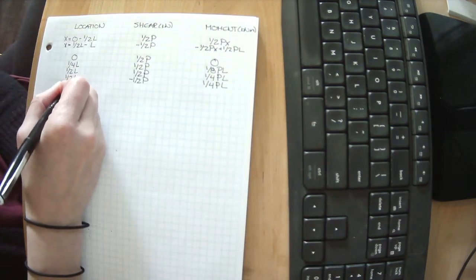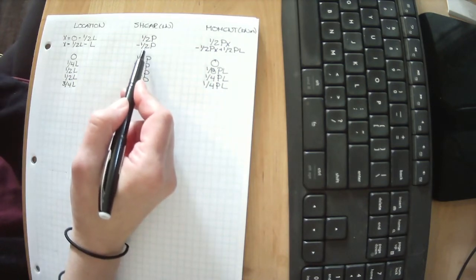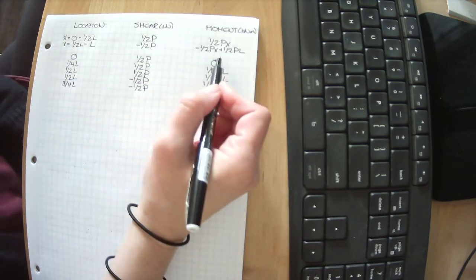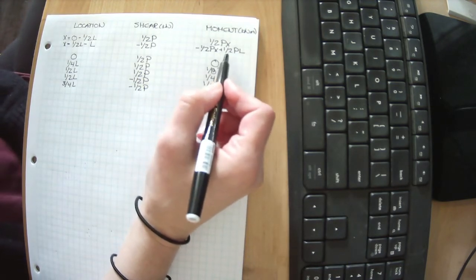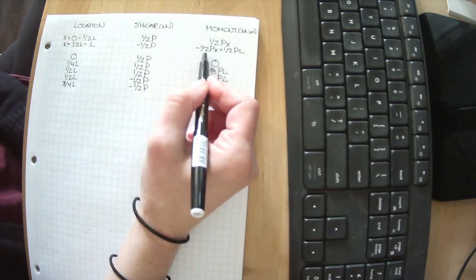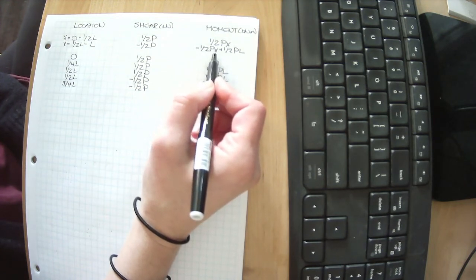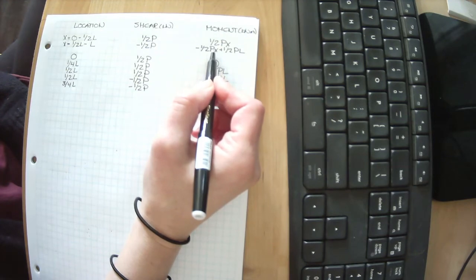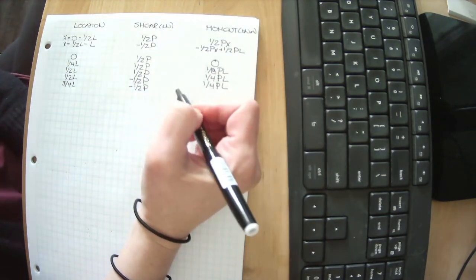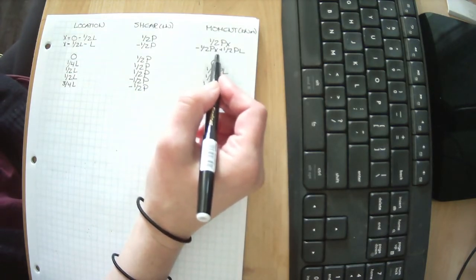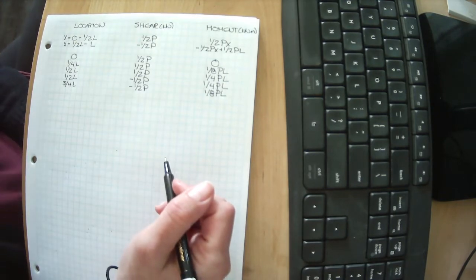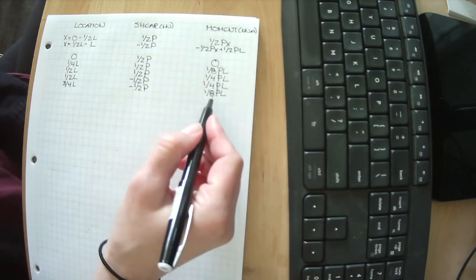All right, let's do 3/4 L. There is no x in this, so if x is 3/4 L, it doesn't matter here, we still get minus 1/2 P. So if we plug 3/4 L into this, we have minus 1/2 P times 3/4 L, plus 1/2 P times 1. I'd have to go through and do it slowly. I'm going to tell you, if we plug that in as 3/4 L, it's going to work out to be 1/8 PL. Trust me, go through and do it slowly. Go back to your basics and do it a step at a time. Just multiply everything out. It's going to work out to 1/8 PL.